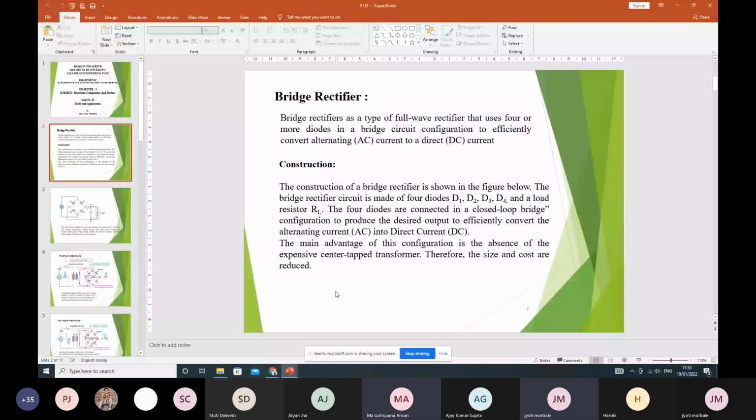In the previous step, we have seen the transformer which was used as a center tap transformer with two diodes in a full wave rectifier. Now to eliminate the use of the center tap transformer, which is rarely used, we go for the bridge rectifier. So in a bridge rectifier, remember, a regular normal transformer, जैसे हमने half wave में use किया था, वैसे ही transformer use होता है, ना कि center tap वाला transformer. So this is the advantage of the bridge rectifier. The center tap transformer is not required, so that ultimately reduces the cost.